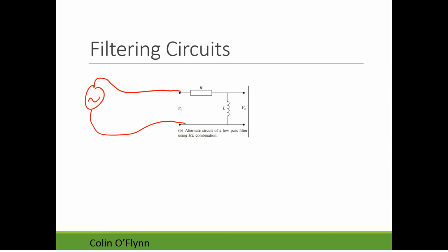So you originally had a 1 or 2 volt signal you can easily read. Then all of a sudden at the output here, maybe you have 100 millivolts. And this is because you have a series resistance effectively in your sensor, and the filter is loading down the signal such that it ends up being very small.